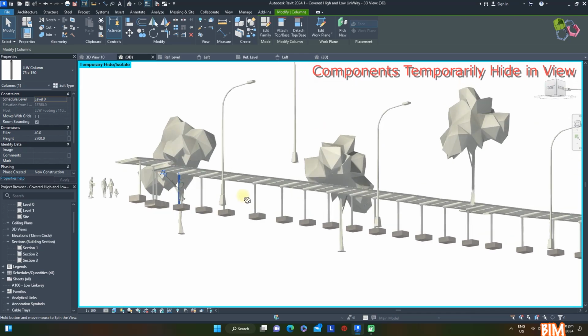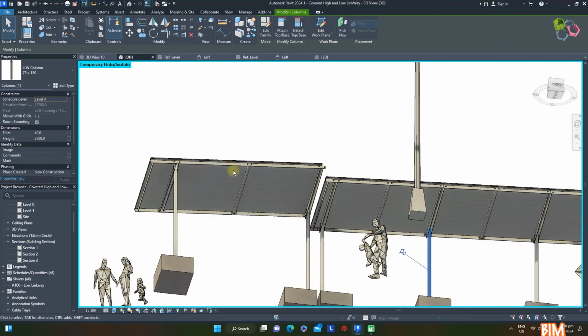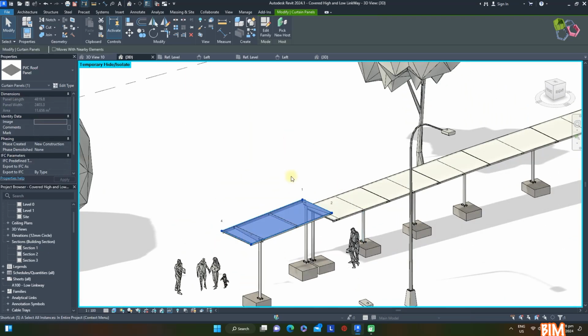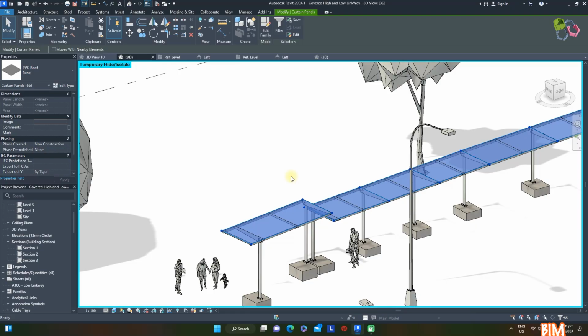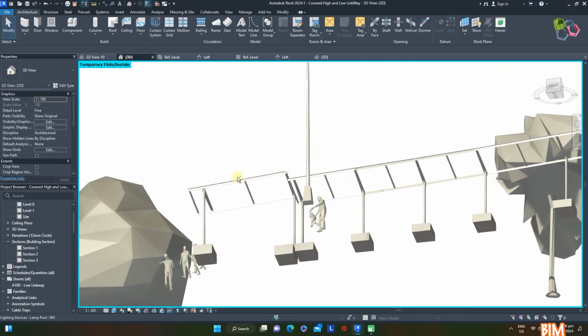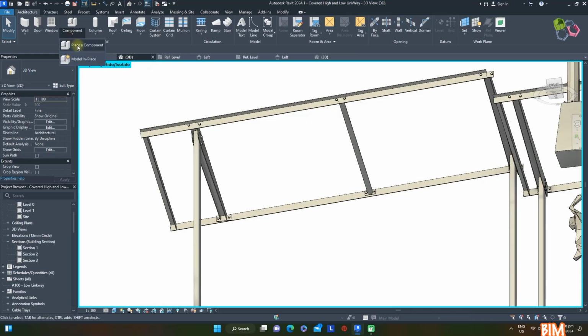Let's orientate this 3D view. We should hide the roof component as well. Select these roof elements. From the keyboard, shortcut SE for select all components. Shortcut HH for hiding components. Now we can place our feature in the rafter more easily.